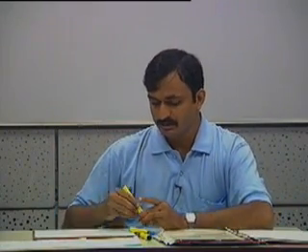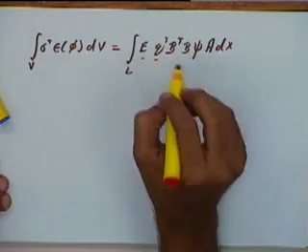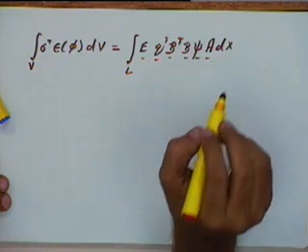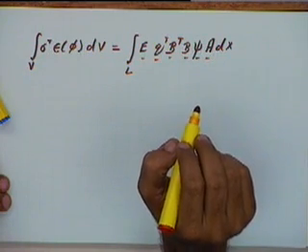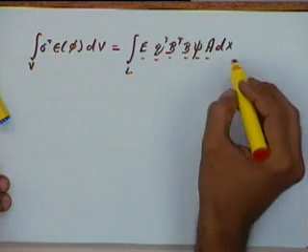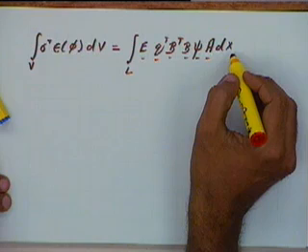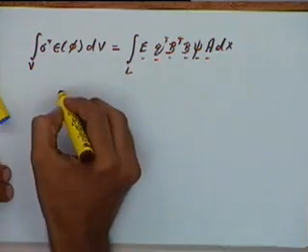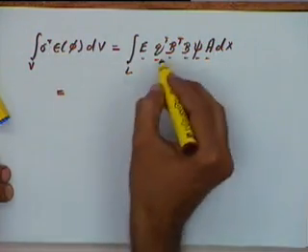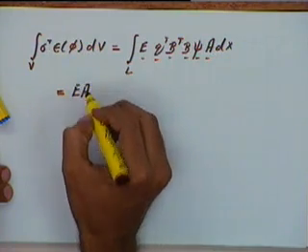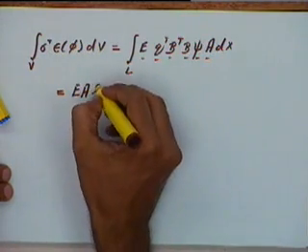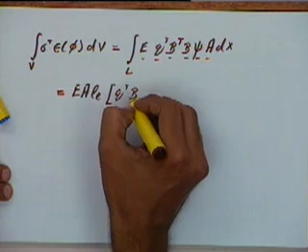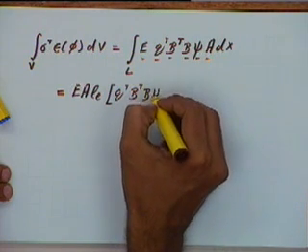Now in this you will notice that E is a constant, Q is a constant, B transpose B and psi and A, they are all constants. They do not change with x, and the integral of dx is nothing but the length of the element. So if I put all these values here, this will be equal to E into A multiplied by integral of dx, which will give me LE, multiplied by Q transpose B transpose B psi.